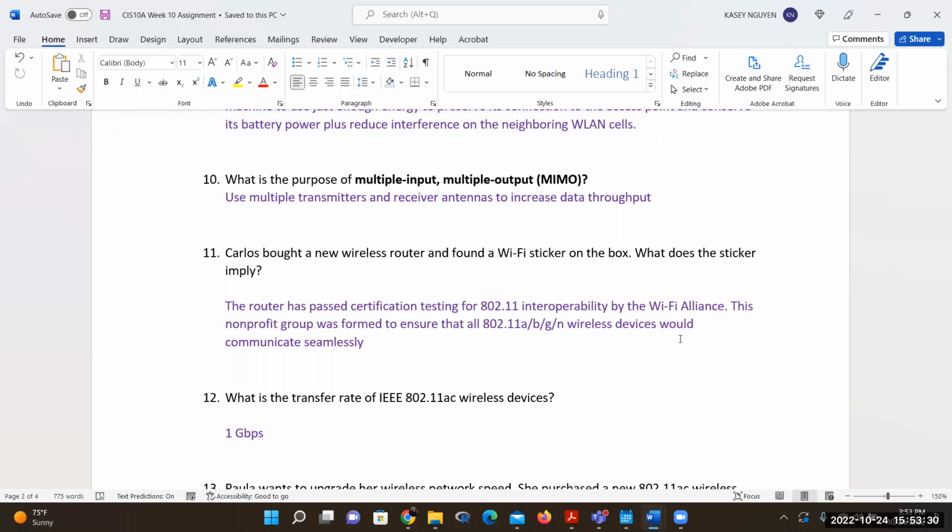And then we would have to use some wireless capability to be able to do that. Now, the challenge is that historical buildings sometimes use metal plates in their walls, and that bounces the signal. So before you design that network, you have to trace and see how your signal would be. Fluke makes great tools for that.